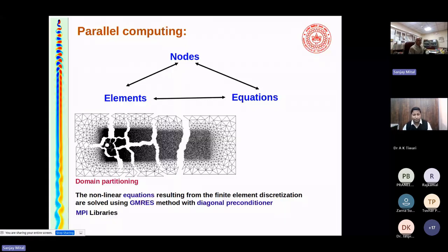I'll just say that it's not just enough to model these equations. You also have to have a way to compute them quick, very fast, to do large scale calculations. So we've spent some time on parallelizing these codes, both on shared memory and distributed memory. So often one uses a method called domain partitioning, where if you have unstructured grids, then you try to make small subdomains of elements that are very close to each other, so they are neighbors, because communications are very difficult on a cluster.